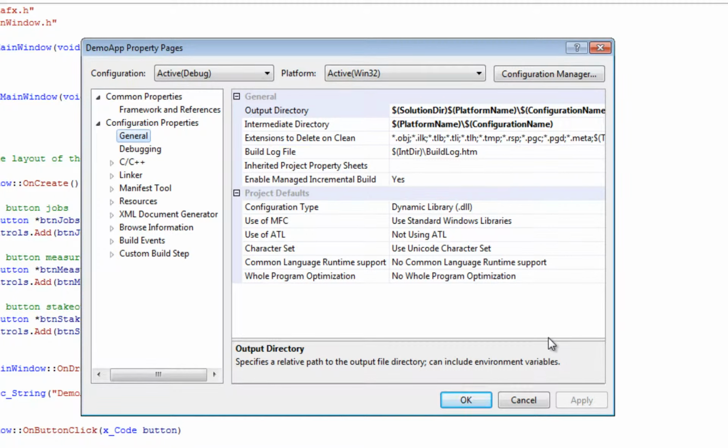First of all, many people think that because they're developing an application, they are creating an exe file in the end. So they ask, hey, I'm building my application, my build runs nicely, so I don't have any build errors. Why don't I see an application in the end? The thing is that we actually don't generate an exe file, so we don't generate an application. We create a DLL that gets loaded by Trimble Access. So think of it that Trimble Access just looks at what kind of applications are available, and it loads them and displays them for you. So you're not really creating an application, but you're extending an existing application via a DLL that gets loaded during the system start.